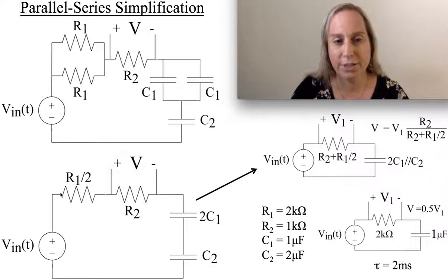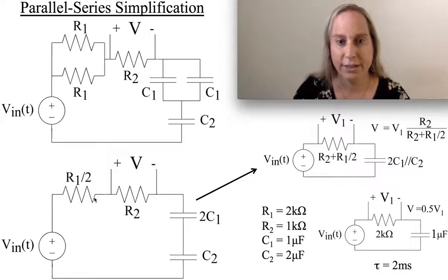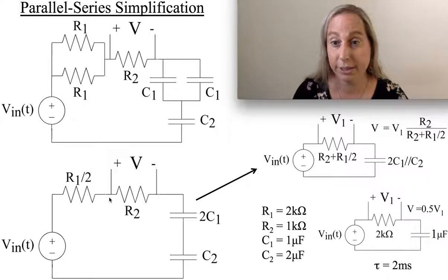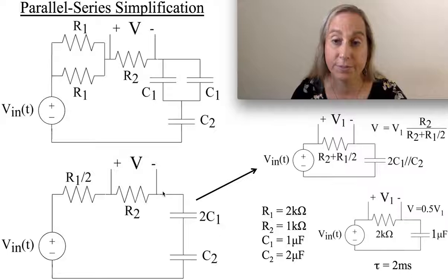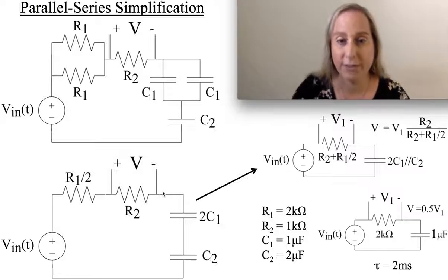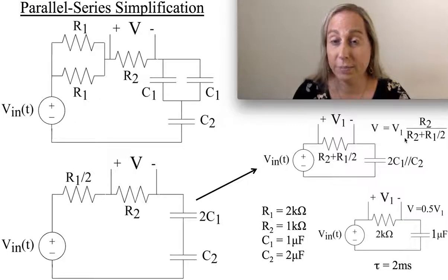Notice the total voltage across here and the voltage across this resistance. You might recognize that this is a voltage divider. If you don't recognize it immediately, you can write KCL at this node and pick this up pretty quickly. What it means is that this voltage will be some fraction of the total voltage across these two resistors. I'm going to keep account of that off to the side here so I remember what I'm looking for in terms of my numbers.